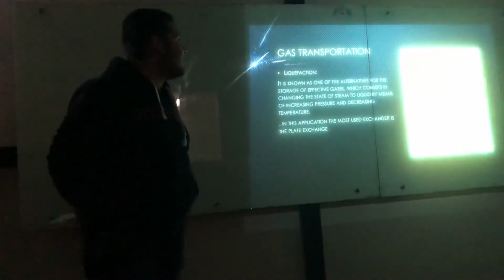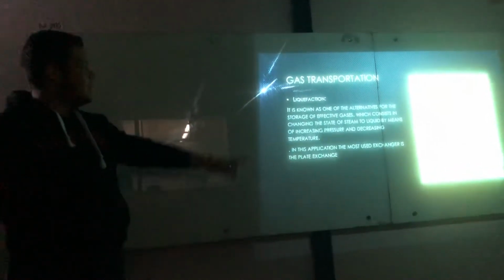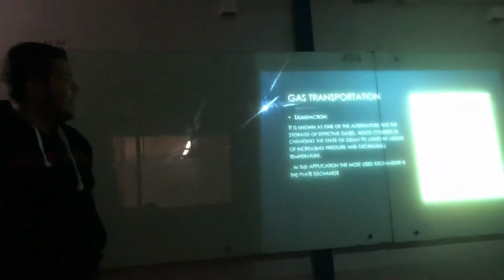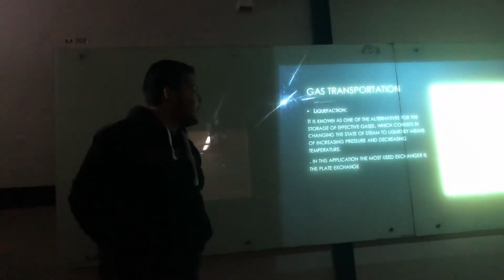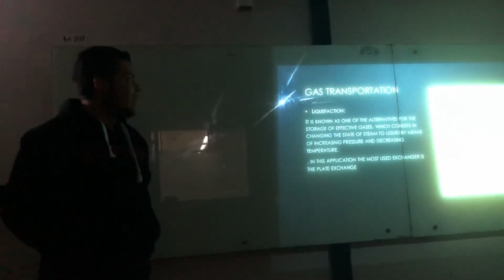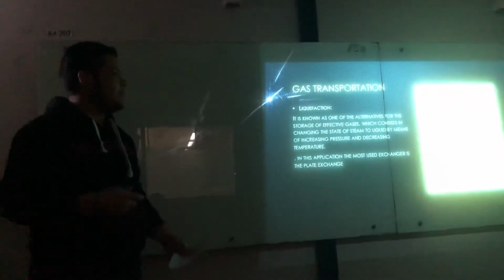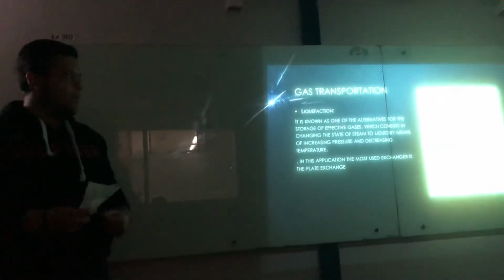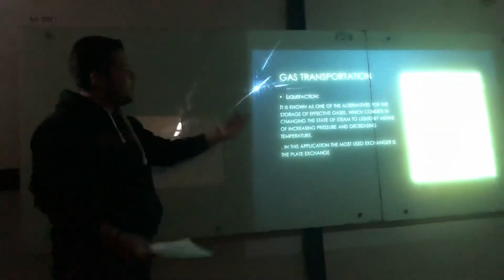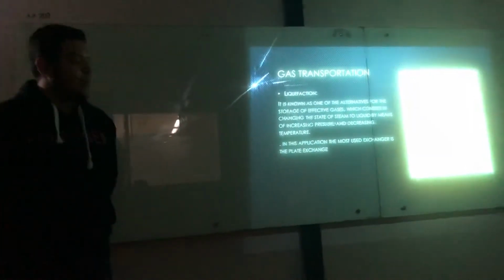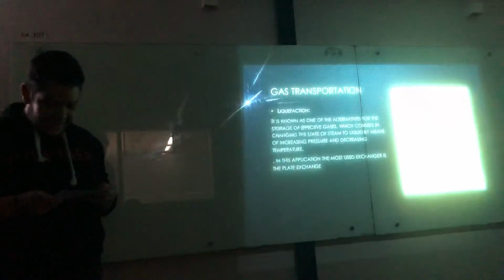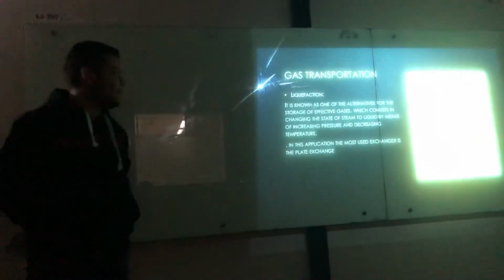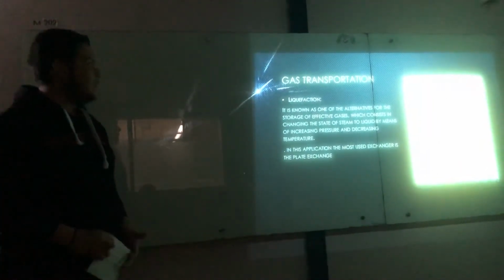In this part, we have a diagram of the liquefaction process. This is composed of a compressor, a heat exchanger, a valve, and a liquefaction chamber. First, the gas goes to the compressor, where work is applied. At the moment the gas leaves the compressor, it is at room temperature and compressed. After that, the gas goes to the heat exchanger where the pre-cooling process takes place.